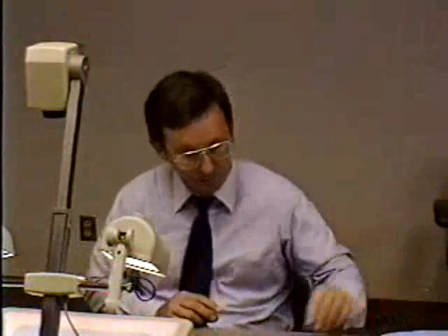Okay. Well, let's look at pumps. We've looked at different aspects of pumps, but let's continue here. The basic concept here is that there are two relationships between discharge and head. We've been talking about the discharge-head relationship for a piping system, and we're going to continue to do that. We're going to call that a system head curve.